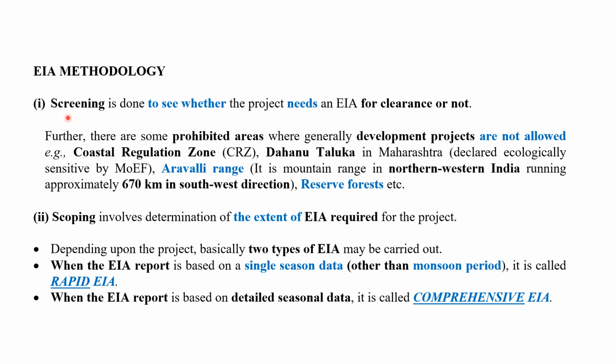The first step which we have to carry out as far as the EIA is concerned is screening. Screening is done to see whether the project needs an EIA clearance or not. So that also we have to find out in the beginning: whether any development project needs an EIA or not. Is EIA required for this project or not? That we have to find out, which comes under screening.